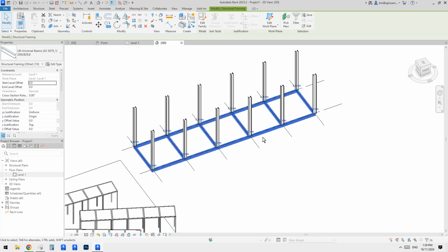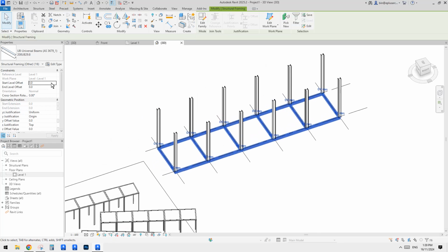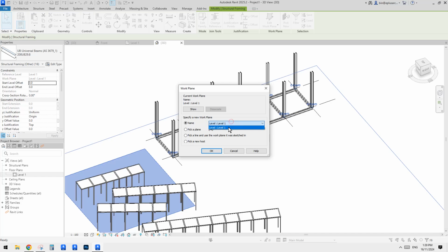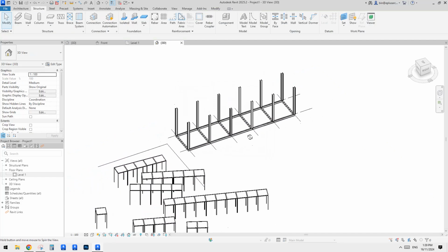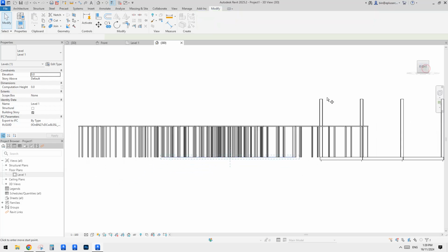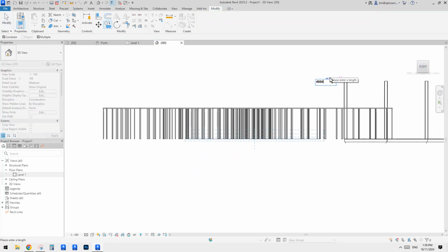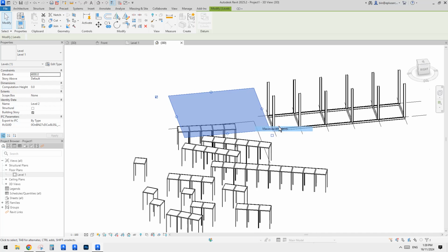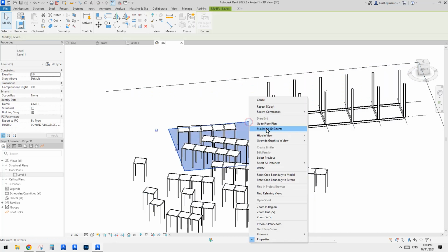onto a floor plan. So we can just select all, maybe I'll change them to edit to a plan. We only have one level in here, so that's fine. I'll select this level and copy it up, maybe 4 meter. Okay, so now we have another level, right? So maybe I'll just maximum 3D extend.